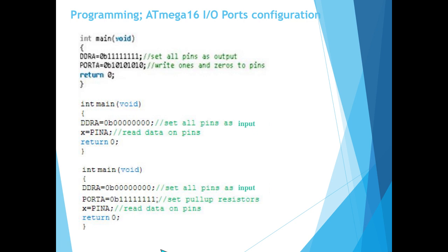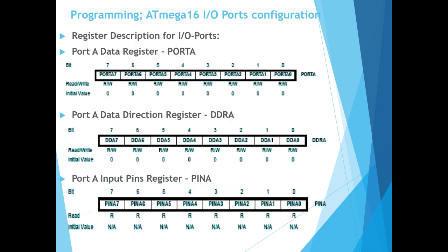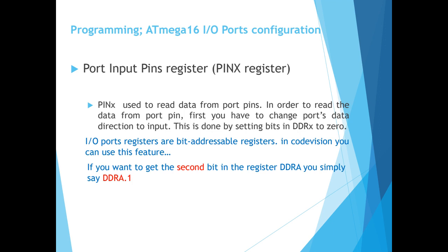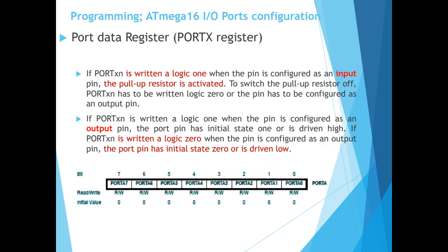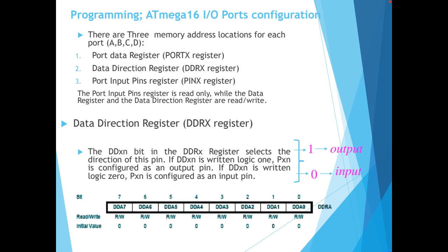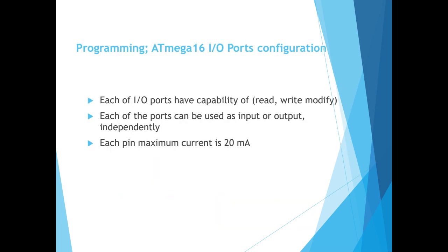When we want to activate the pull-up resistor, one of the questions was about the pull-up resistor. Actually, we use the PORTX register, or on the other hand, this is called the data register. We said that there are three kinds of registers, as you remember.